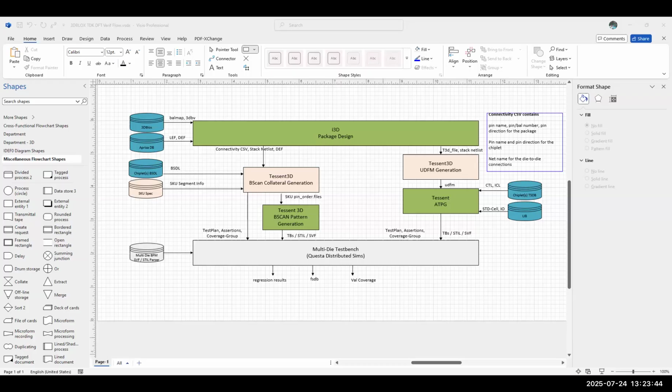Typically, I don't think SIP integrators are going to be retesting wafers, right? I would anticipate these wafers are going to be sorted by the wafer provider. Now, it is possible that maybe not. Maybe it's an unbumped wafer and you're doing some post-processing layers. One approach that I've seen is, for hybrid bonding type devices, practically speaking, you can't probe those. So one way of testing those is you can basically do a buildup, post-process the wafer, deposit a bunch of probe pads, test it, and when you're done testing it, strip that away.